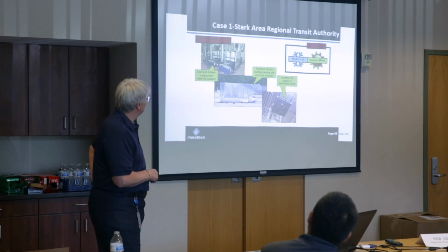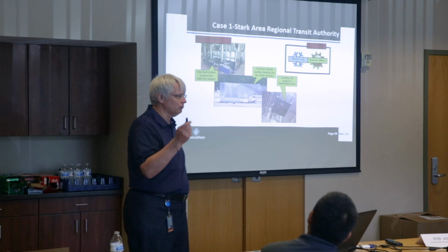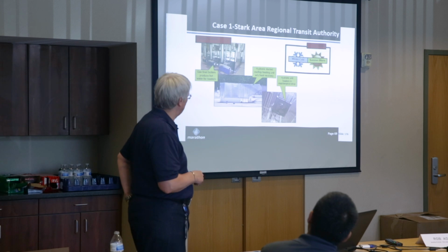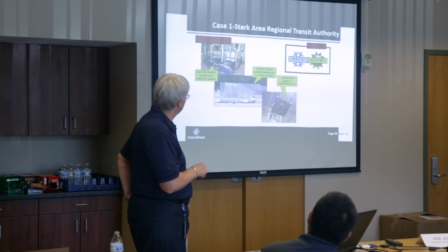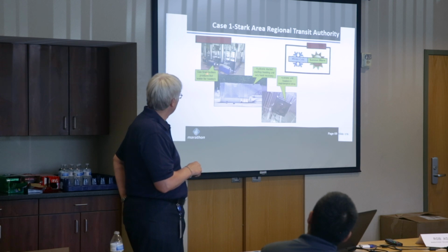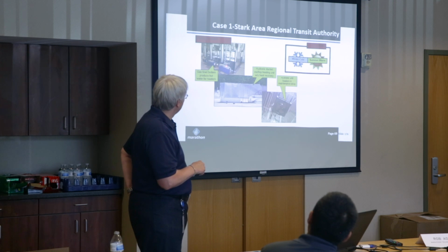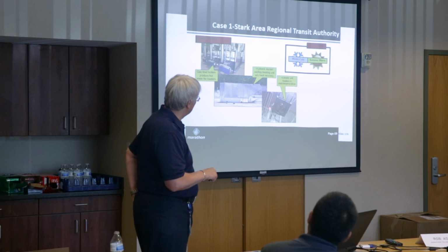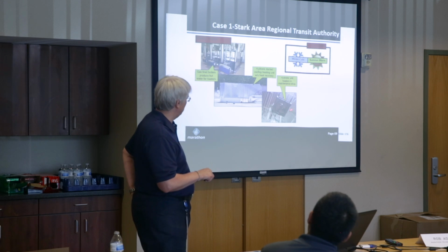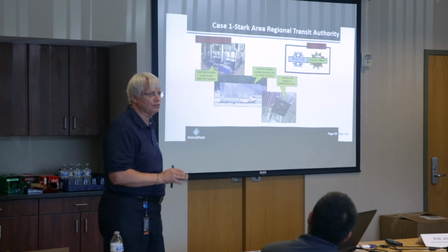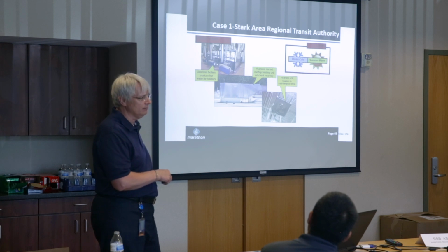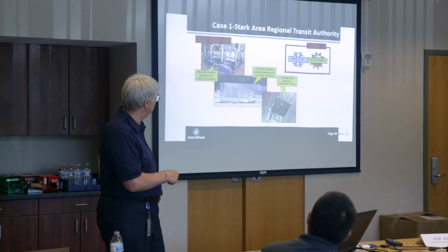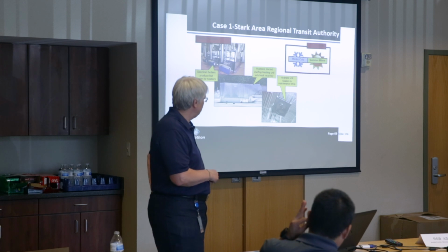So their heating system, they have several different types of units, but they are coming off these 3 boilers, and we'll take you in and show you the boiler room. But anyway, they're producing the hot water, and then they have unit heaters throughout the area. You can see here, these are hydronic unit heaters, so there's no open flames, it's just hot water. And then they also have hydronic coils in their roof-mounted makeup air units as well. So they're not using any heat recovery.